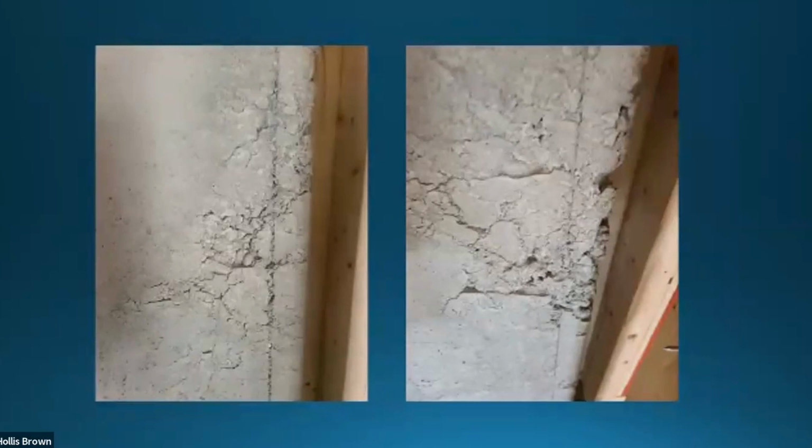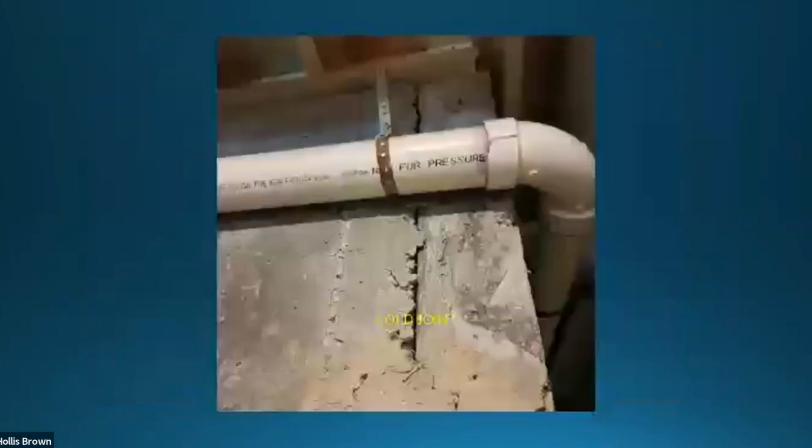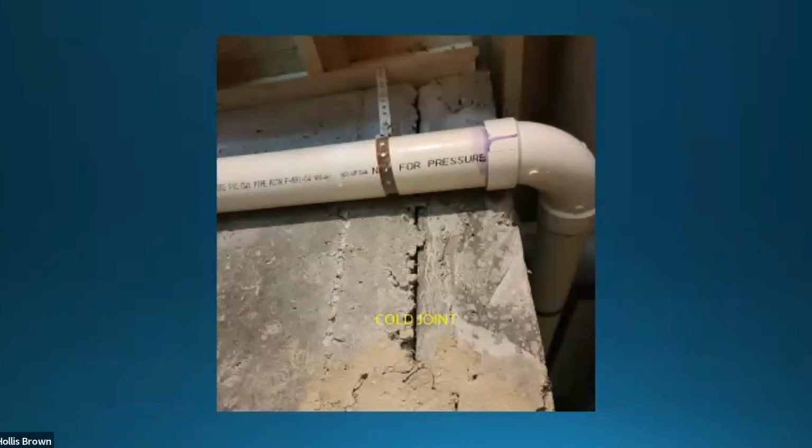That's too dry there, and it really wasn't vibrated. That's a cold joint. You never want cold joints. They're never good, but they must have had more than one pour and they waited way too long and they didn't bond to each other.